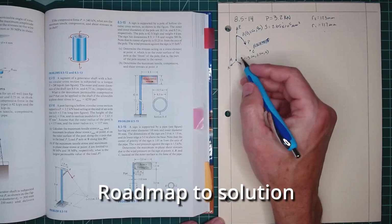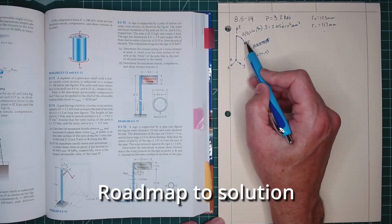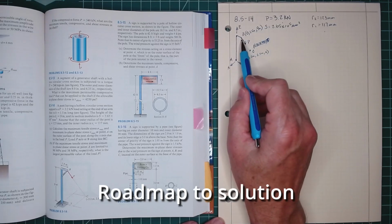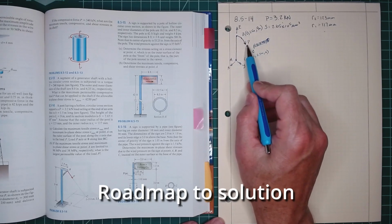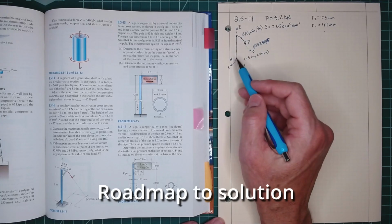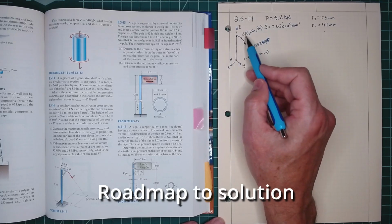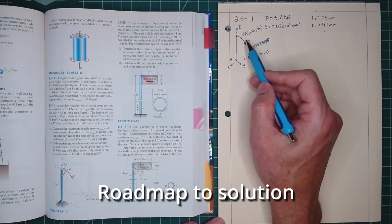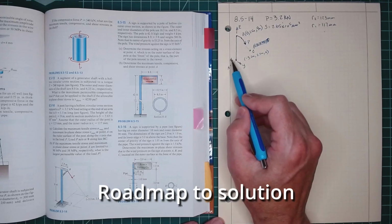Now, at this point, what we need to recognize is that this force P, and we haven't looked at it specifically yet, but when we look at it cursorily here, is really three-dimensional. So we have an X component, we have a Y component, we have a Z component. All of these can be placed at A. So we can replace force P at A, and those forces are also going to be creating moments about point A.